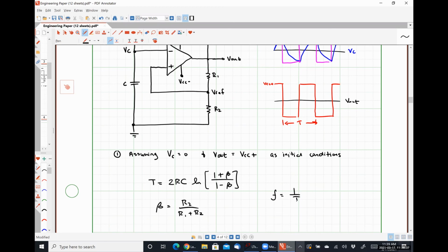Or if you're a guitar pedal dork like I am, this is how you can make a tremolo circuit. You can light up an LED at specific intervals and then use a photodiode to translate that into turning your voltage on and off, which is exactly what a tremolo unit does for a guitar effects processor. So you can use this stuff for lots of neat and nifty little things.